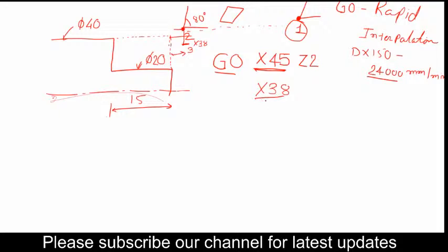Since I am writing only X38, Z will remain the same. So Z will be 2. If I write Z2, it's fine. If I do not write Z2, then also it is the same, because I'm just moving in the X direction only. Okay.